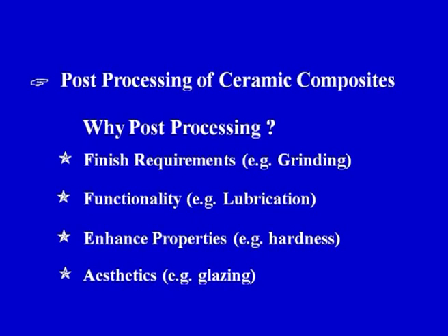So on your screen you can see why post processing of ceramic composites is required. There are 4 important points which necessitate the post processing of ceramic composites. First and foremost is the finish requirements, and in finishing we can undertake the process of grinding. Sometimes in certain applications we require a very high surface finish of the product. So for finishing, grinding is one of the most commonly used processes.